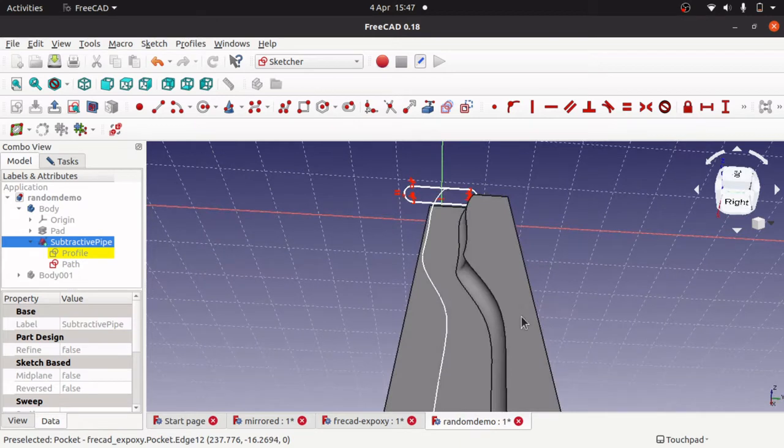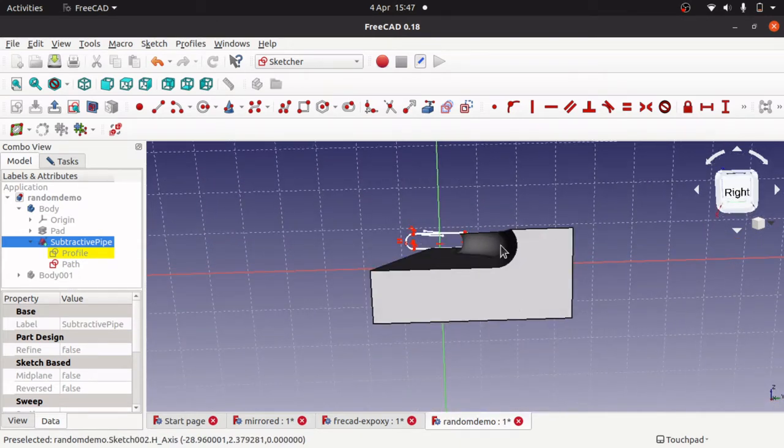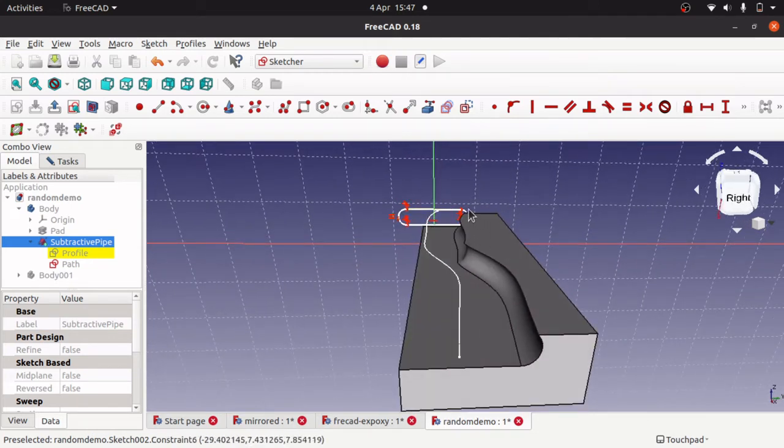If you look at this feature here, it's actually a fillet that goes along there, but it's actually created by the profile itself. So I wouldn't actually do that. I would come in here and create a square profile and then use that to create a path through here, and the tool path will follow that path, and then use a tool and CNC swap over to a fillet bit to remove this material here.